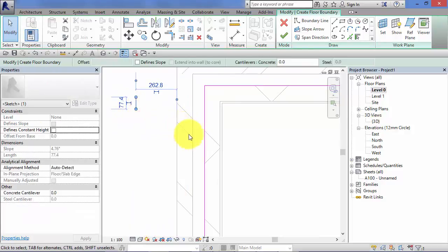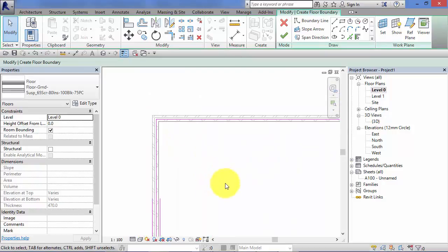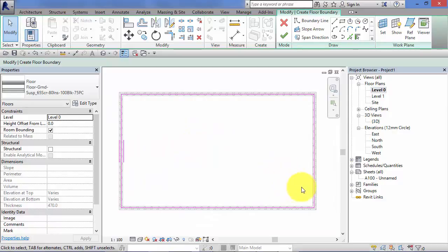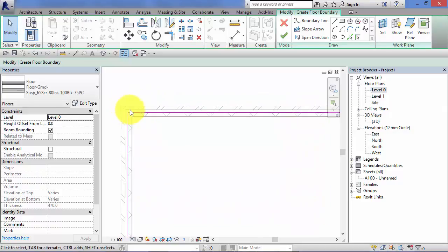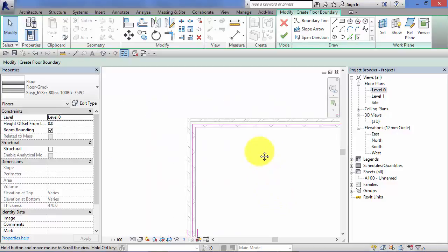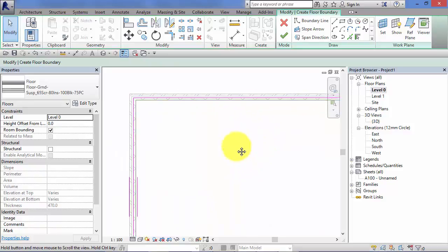So to begin with, a lot of people when they start out with Revit find the sketch mode can be quite frustrating because sometimes it's not clear or not self-evident why Revit is complaining about the sketch that you've drawn. Likewise, even if we added another pink line on top of one of these, that wouldn't be acceptable. It's just got to be a closed loop with no straggly bits or no gaps.